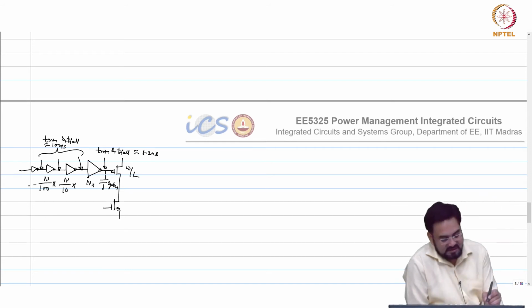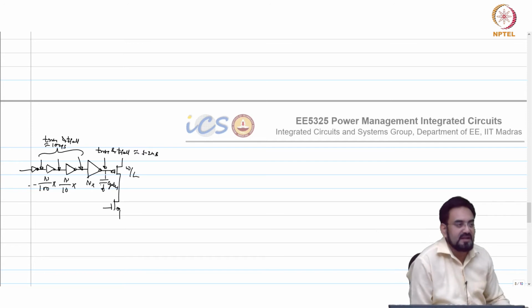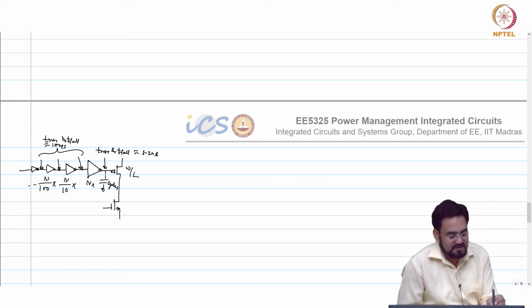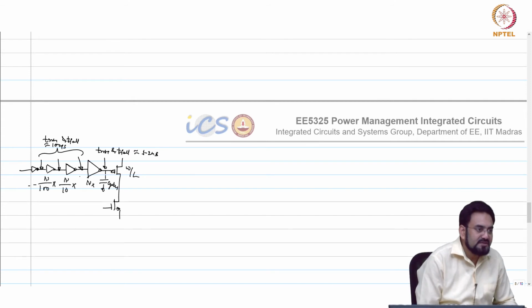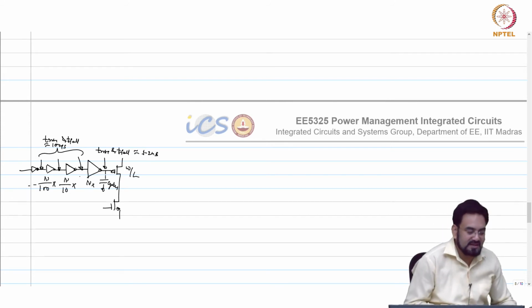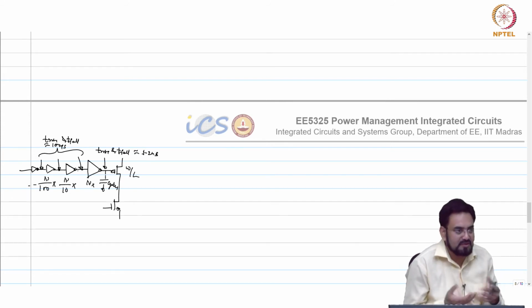Which means the slew rate at the gate is mostly driven by the final inverter, and before that you are simply making sure that this whole chain is able to drive the gate cap of each stage. That's why you progress gradually rather than simply putting 2 or 3 inverters.